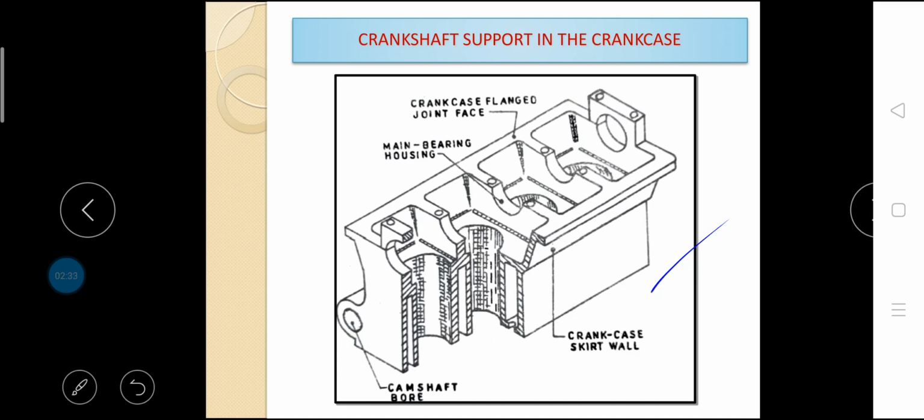The materials generally used for cylinder block are grey cast iron and aluminium alloys. Grey cast iron is so called because of its grey appearance when fractured. In this, the carbon is present as flakes of graphite, which makes it more wear and corrosion resistant, apart from its better machinability. The aluminium alloys used for cylinder block are the aluminium silicon types, which have good casting properties, are corrosion resistant and retain their strength at moderate temperatures encountered in the engine block. Out of these two materials, cast iron is the one which is mainly used because of some advantages.